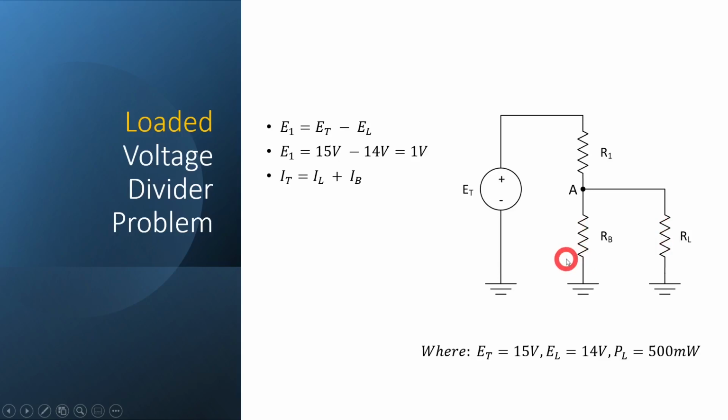Remember, a parallel circuit is a current divider, and the current is divided right here at point A. So Kirchhoff's current law tells us that the sum of the currents coming into point A has to equal the sum of the currents going out of point A. Well, we only have one current coming into point A. We have two coming out. So here are the two coming out. If we add those together, we get the 1 that should be going in, which also is total current. And that's why this is a series parallel circuit, because at least one component in the circuit carries total current.